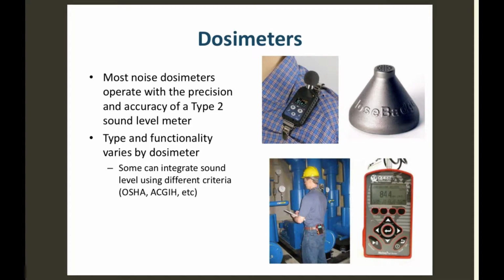For the other instrument, I blew air into it without making any sound. Yeah, it bumped up. That's why you'll notice on the dosimeter, it has a windshield on it. And you should probably have the windshield on the sound level meter.